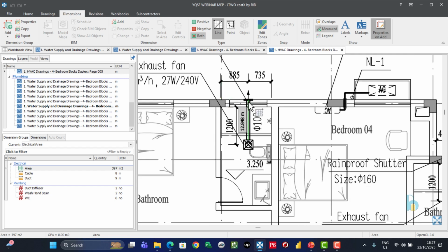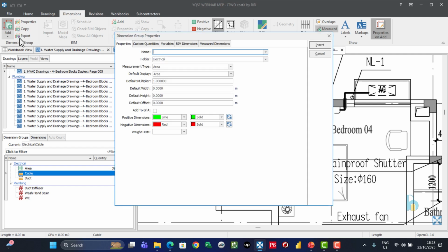To measure a drop, you are going to measure it using the count, not the meter. So here we can say deduct vertical drop. I'm going to measure this using the count. Then under this default height, this is where you specify the height of the drop.